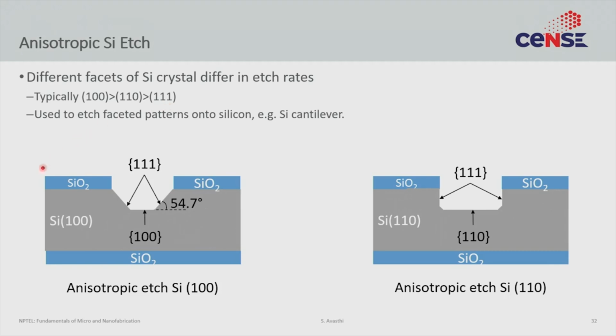Now, one area where this is very useful is actually in MEMS, where you want to make mechanical structures of various size, say silicon cantilever. Towards the end of this course, we actually have a whole module on a lab visit where you see how a cantilever gets made. We will also discuss the cantilever in a little more detail down the line. But the fundamental thing that all those techniques require is the ability to do anisotropic etches, and wet anisotropic etches are just one thing in your library of unit processes.